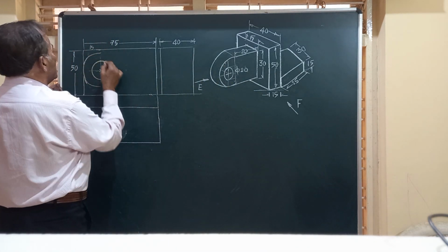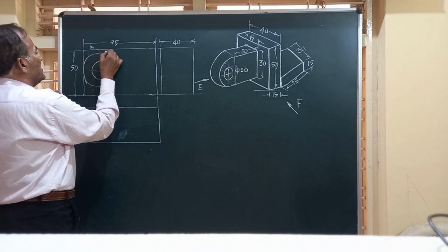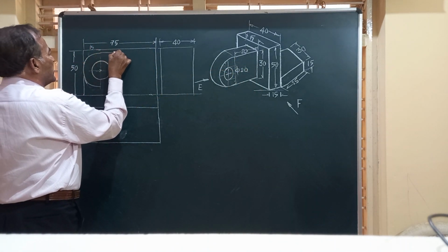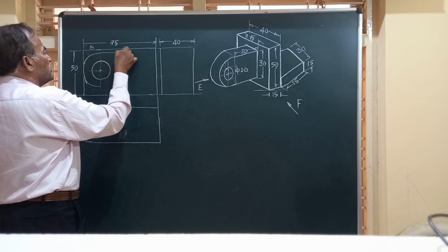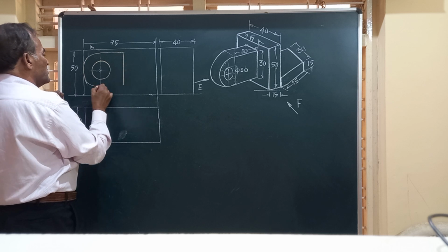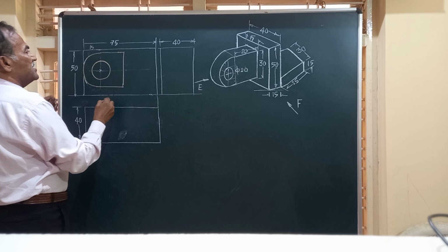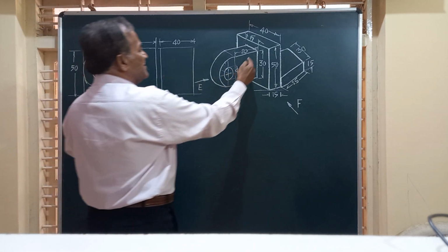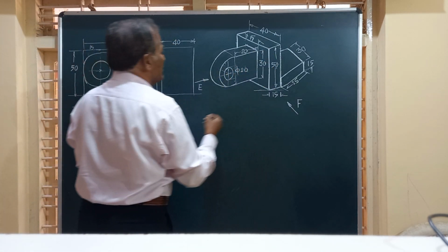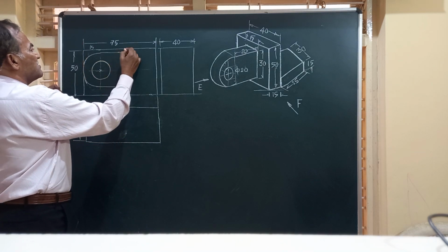Friends, from there I am going to draw this horizontal line of length 20 mm. Parallel to that edge, we are going to have a rectangle here, and this is the center line we locate here. Then you have a 50 millimeter length line, this is 15.